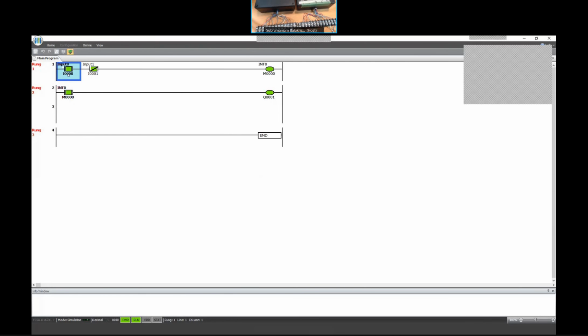The internal relay became true, and the internal relay as the output normally now has come back as an input and is setting a hard output Q. Absolutely possible, no issue.